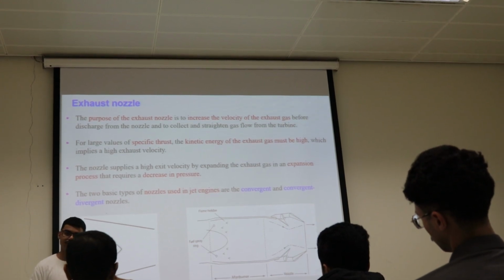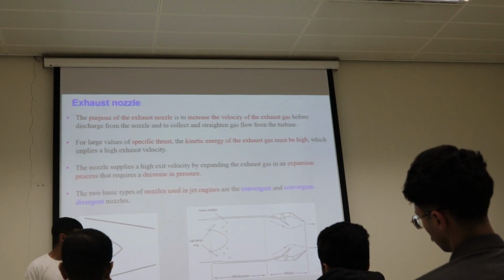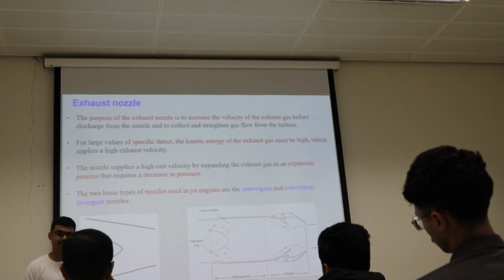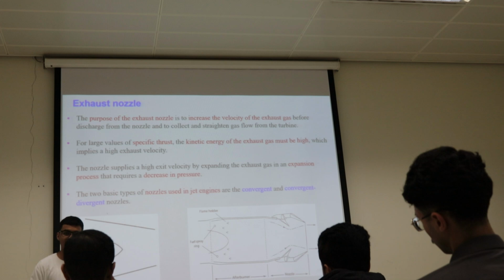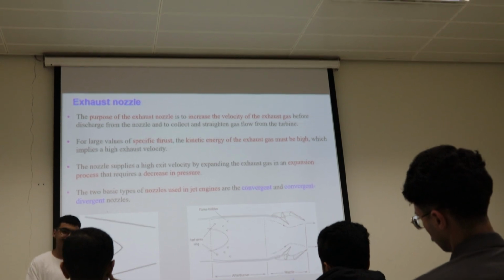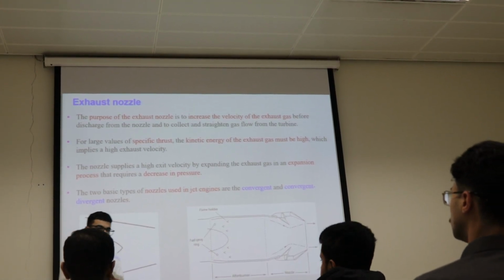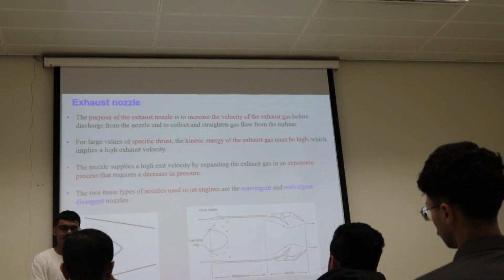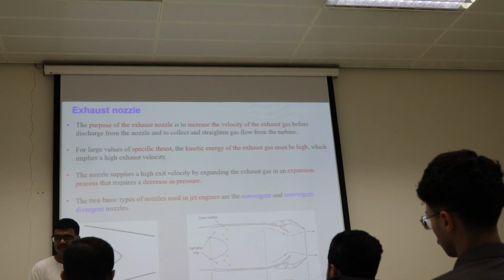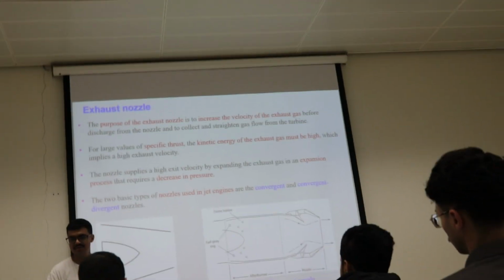As we said, the operation should be all the way under what? The design condition. You see the variation of back pressure with nozzle operation, so we have to have the nozzle working under the design condition all the way. But what will happen if the back pressure is changed, or the supply pressure is changed, by burning more fuel and all of this? That means the design condition will be changed. So I can control the design condition by controlling what? The area ratio, exit area to throat area, to achieve that the nozzle is working under the exit design condition all the way. You can imagine the afterburner is like a turbo in a car to increase the speed momentarily.